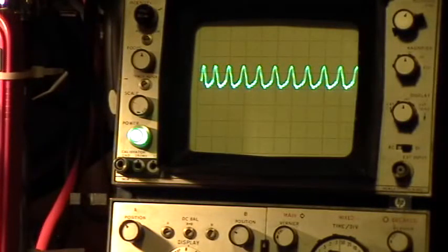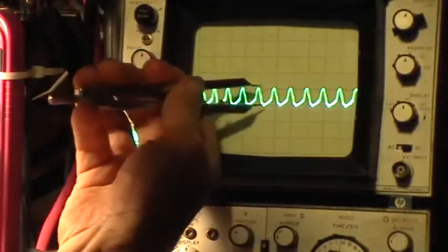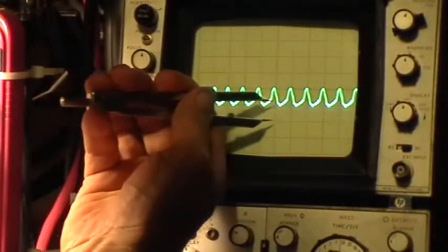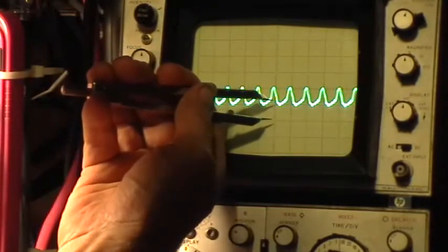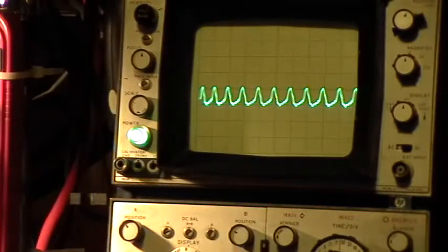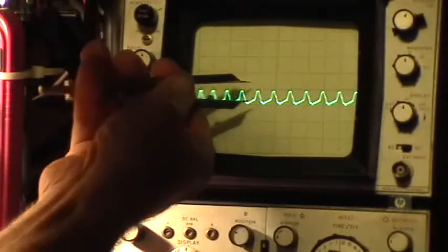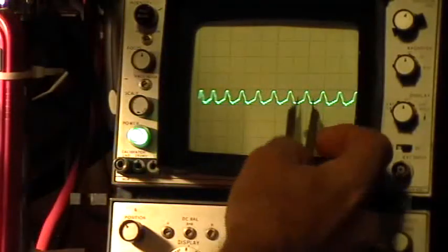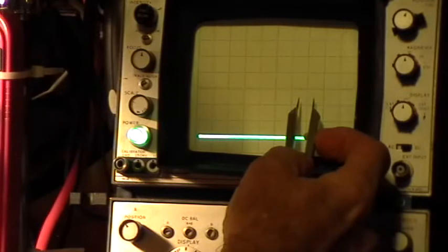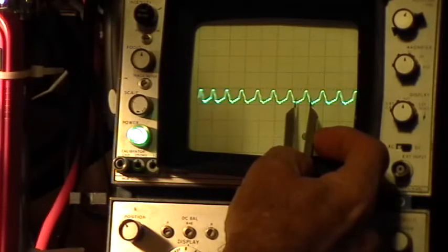Now I'm going to go to the negative pole of that battery, right there, and so now we're at just about 11 volts. Now I'm going to go to the other side of that jumper, another 4 inches of wire, right there. That made a big difference. See, the voltage level from here to here doesn't really change, but the amplitude of the oscillations changes, right? This is just on the other side of 4 inches of wire.